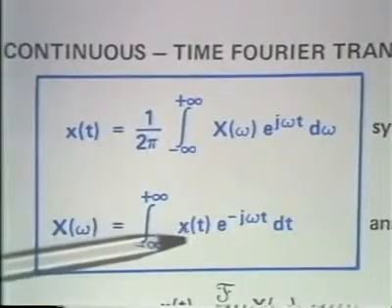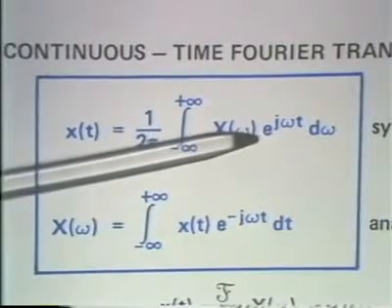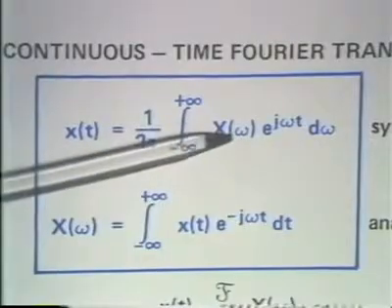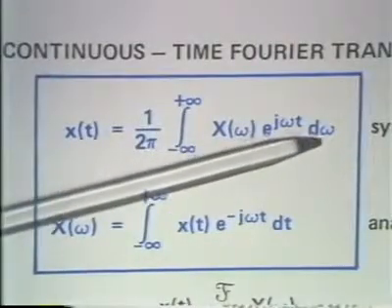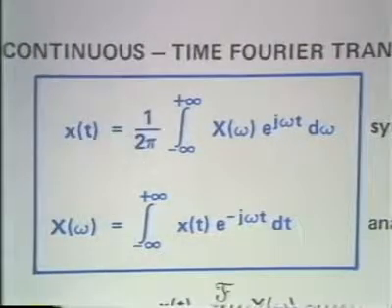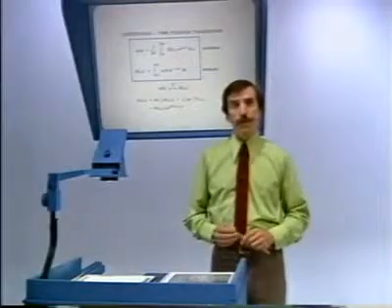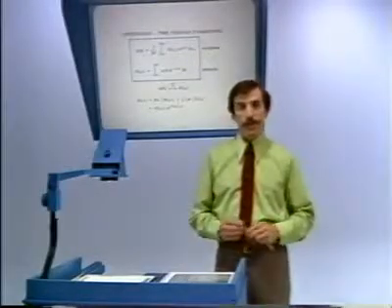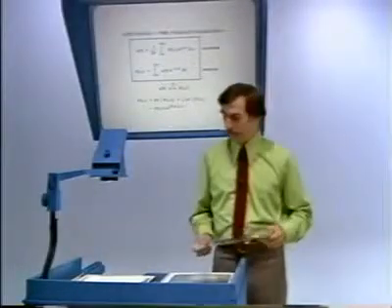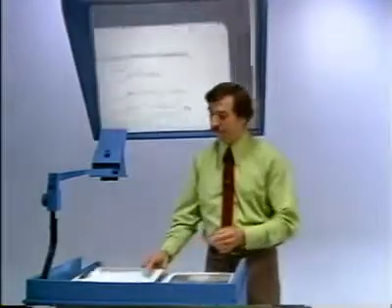So essentially, in the decomposition of x of t as a linear combination of complex exponentials, the complex amplitudes of those are, in effect, the Fourier transform scaled by the differential and scaled by 1 over 2 pi. Now, as I indicated last time, the Fourier transform is a complex function of frequency. And in particular, the complex function of frequency has an important and very useful symmetry property.